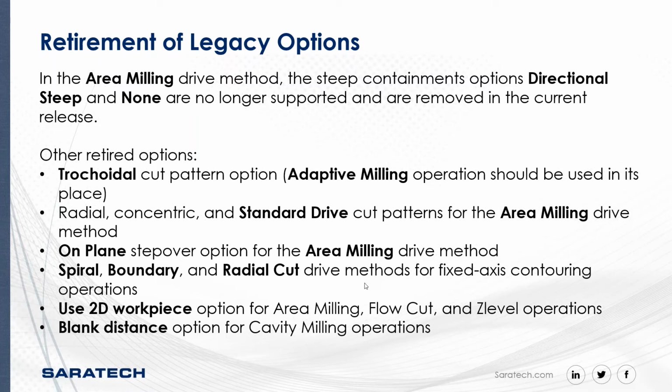Spiral, boundary, and radial cut drive methods for fixed axis contouring operations are removed. They're no longer supported. Use 2D for area milling, flow cut, and Z-level is no longer supported, and blank distance for cavity milling operations is no longer supported. So you will not see these in the operation dialogues.